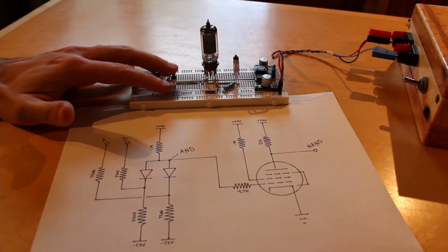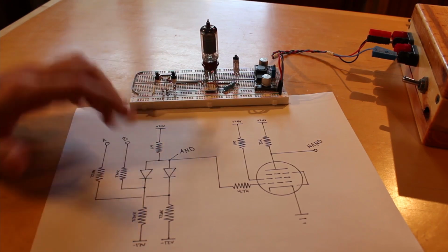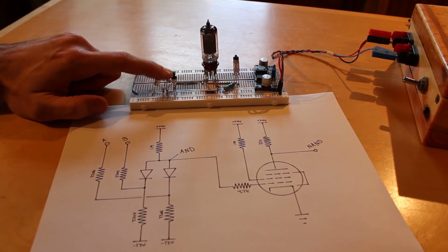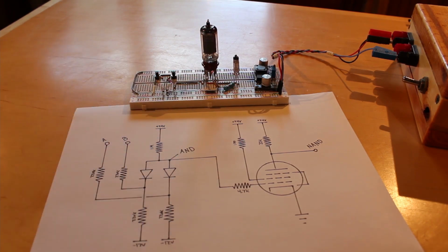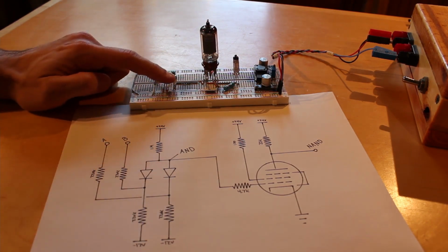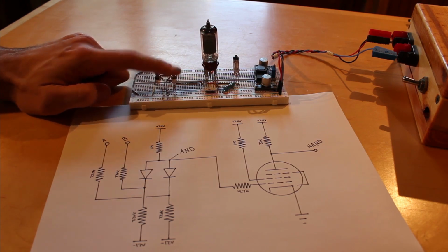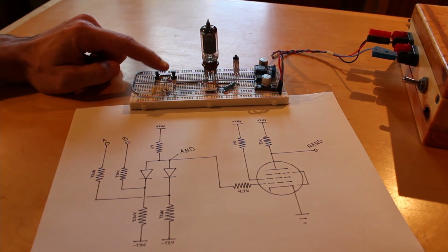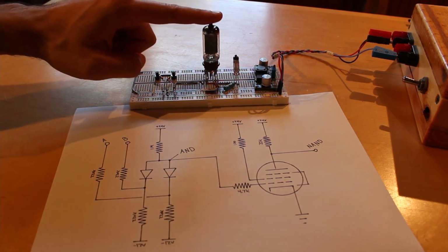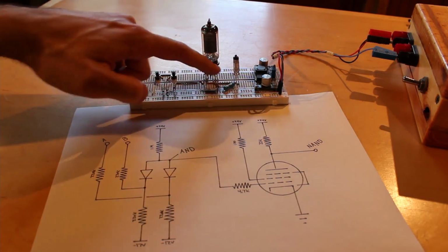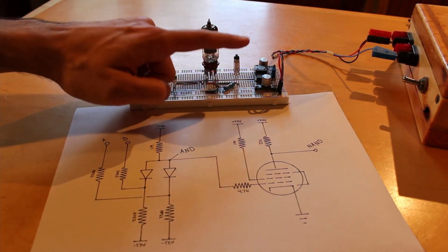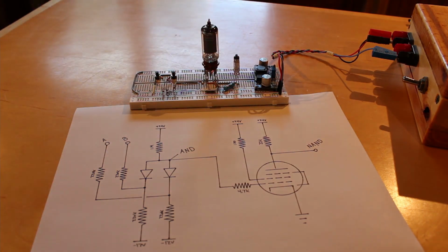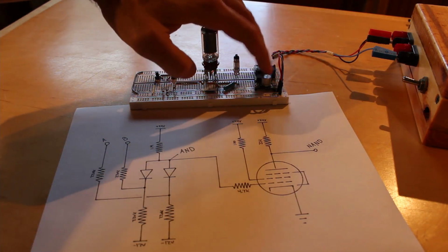All right, I've got my breadboard set up exactly like the schematic below it. I've got my 4 220,000 ohm resistors right here, creating this interesting resistor network on the input here. And then I've got my 2 diodes here and my 1 megohm pull-up resistor. And this is the AND portion of it. And my 2 inputs, A and B here, are going to be these 2 little push buttons here. And then I just have a 6AU6 set up as an inverter over here. And I've got a little VFD that should display the output of it. So it should be on unless both buttons are pushed. And then over here on the far right, I've got my little regulator that's going to drop the 24 volts input down to 6 volts just to power the tube here.